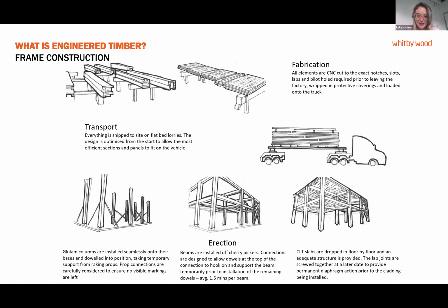It's very, very similar. The only thing I'd say is that the beams can all basically be done from cherry pickers very easily, because it's all very light, as long as you're not high in the air, that is. And there's some nice connection details that I've used on various projects now, where you have a hook on the top of your fin plate connector, which means you can balance the beam in without the installers having to hold it in place whilst banging in the dowels or screwing it up or doing the bolts up. If you hook it on temporarily, then it's all in place.